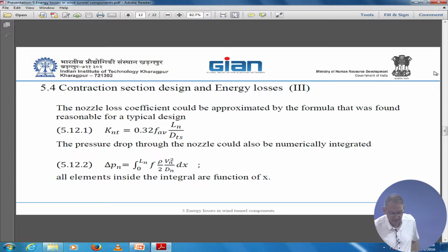So you see here the terminology, parameters that are related to the honeycomb. By the way, a honeycomb can also be made of circular tubes. If you're going to build your small wind tunnel, you just buy hundreds of straws and connect them, and you have a nice honeycomb.